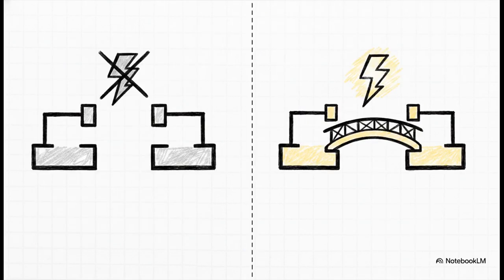Okay, to solve that fridge mystery, we first need to understand the absolute basics. Every piece of automation and electrical engineering out there relies on two fundamental states of a switch. It's either open, meaning disconnected, so the electricity can't flow, or it's closed, meaning connected, allowing the current to pass right through. The big question engineers ask is, what is the switch doing in its resting state? Like when nobody is touching it, is it stopping the electricity or letting it flow? This default state is literally the foundation of how machines are designed.